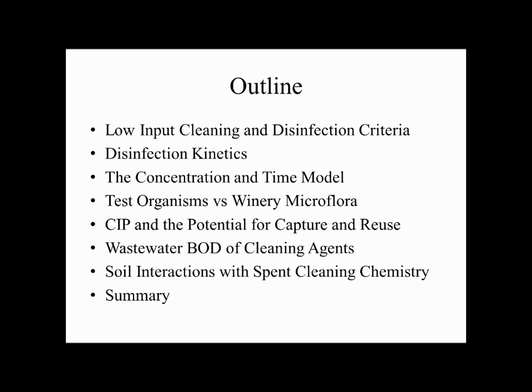And the other thing in our cleaning chemistry is not just that it takes air or it takes energy to break down the organic component into oxygen and CO2 and other things. It's about what's left over. And what's left over from most wastewater ponds that most wastewater engineers don't understand is the inorganic salts that we put in that weren't broken down by the BOD and the organisms.